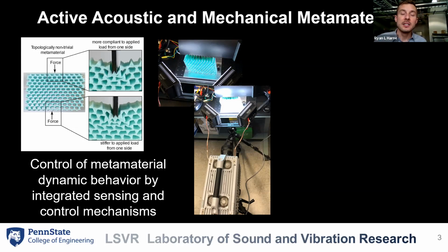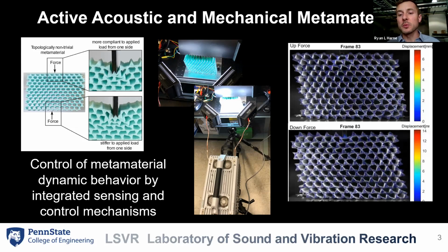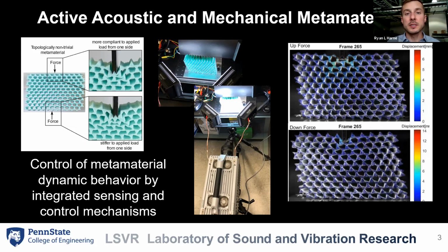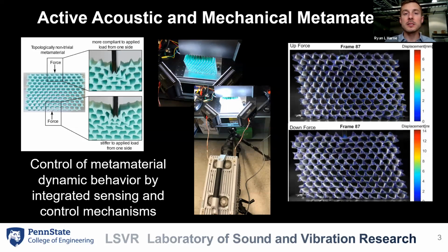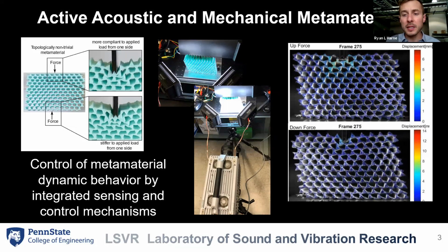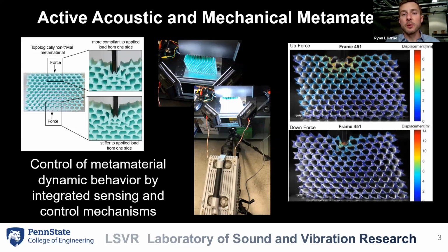There's so much light. So we oftentimes use high-speed videography so we can then use digital image correlation to track the motion of the sample before and during applied loads. So then, in this case, we can map out displacement, strain fields, strain components, and so on. It's a pretty involved and impressive process, but leads to some very insightful conclusions, in this case, about how applied force passes asymmetrically through this polar elastic material.